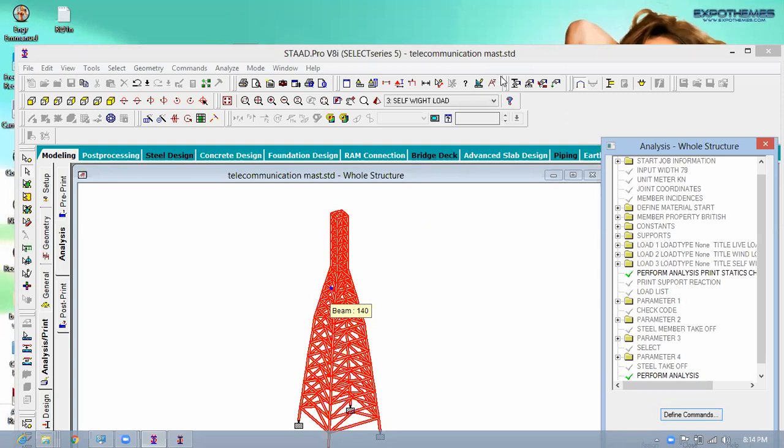So if this is moved to Start Foundation, once you're picking the kind of foundation you want to do, that is where this can actually be pushed. The software already knows that the load is coming on the foundation. That is why we used the support reaction. We pushed the whole of our loads to the support, so that the support will actually react on it.